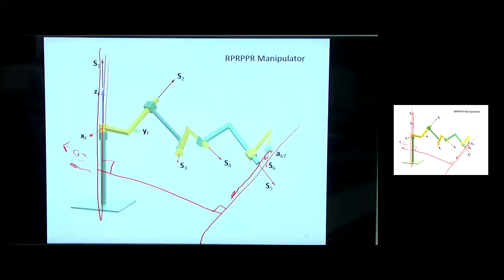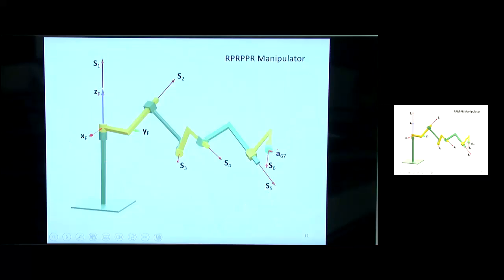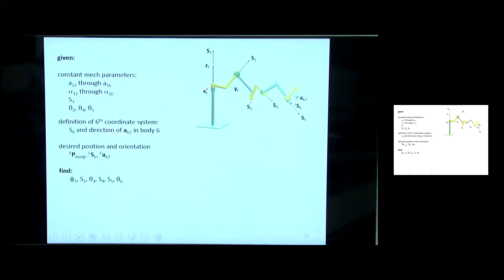So basically, we're taking this reverse analysis problem, and we're turning it into this closed loop mechanism. And what we're going to find is that this closed loop mechanism is going to have 1 degree of freedom, and one of the parameters that we calculate when we close the loop is theta 7. And then when we look at the equivalent spherical mechanism of this, it better have 1 degree of freedom also, or else it wouldn't be in this chapter. Okay. So hopefully the story I'm telling is like, yeah, we've seen this stuff. I kind of see what's coming.